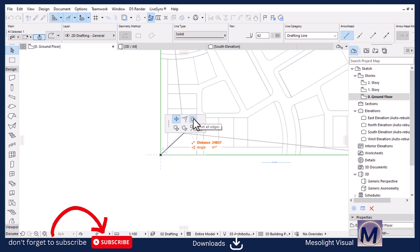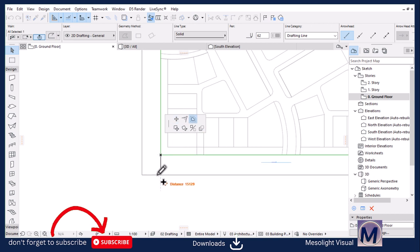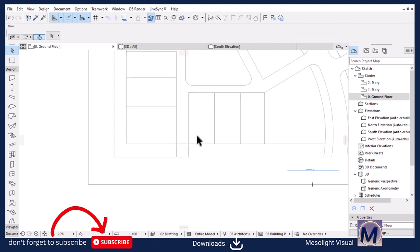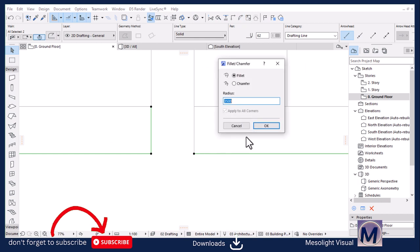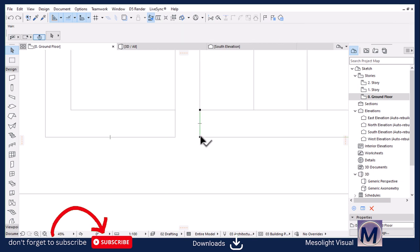So what I'll do, I'll use the offset all edges and then hit Control to add a copy, and then I'm going to have a width of a road, maybe 12 meters, something like that. Perfect. And then I can now go ahead and delete that chamfer because it's a junction. I'm going to have a problem here.